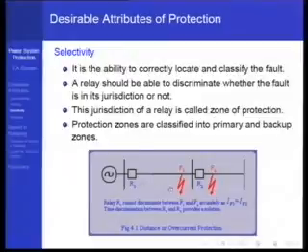On the other hand, if the fault was at F1, what would happen? The relay R2 will not see this fault because this is a radial system with a single source. If it was a radial system with sources at both ends, then irrespective of the fault being at F1 or F2, R2 would have seen it.